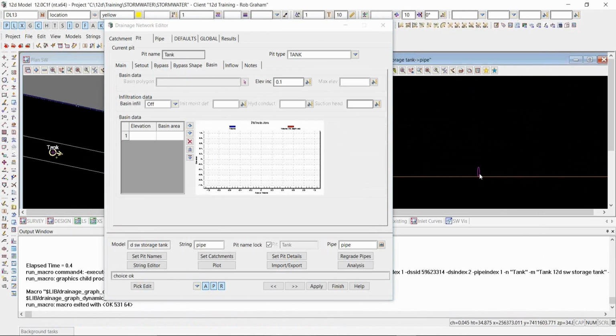And I'm thinking that if I didn't have any storage at the bottom, if I had my orifice in a small depression inside my tank so that it just got completely wet, then that bottom 150 of my tank wouldn't be needed for storage. And my entire 60 square meter tank could be raised by that 150, saving me a bit of money.